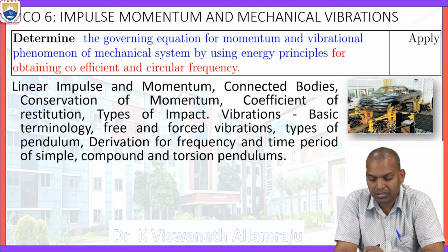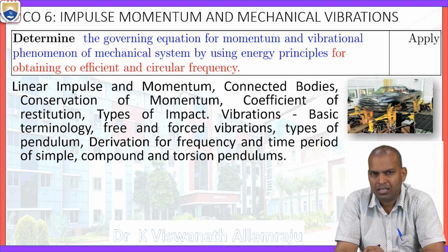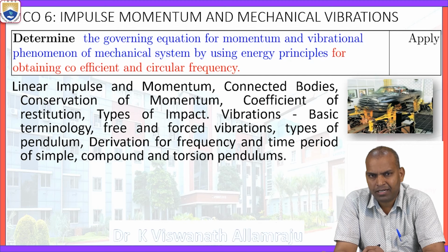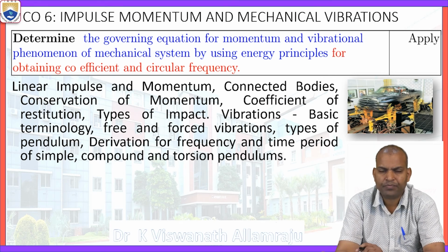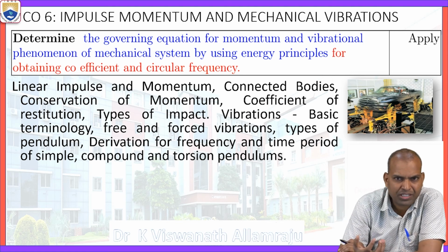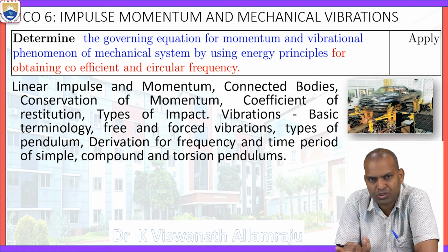Here, under various vibrations, how can the car body sustain them? We are going to use a random vibration system here, not linear vibrations, but non-linear vibrations. The non-linear random vibration test is conducted for any automobile vehicle, space shuttle, aeroplane, or helicopter, because these operate under dynamic forces that vary with time.